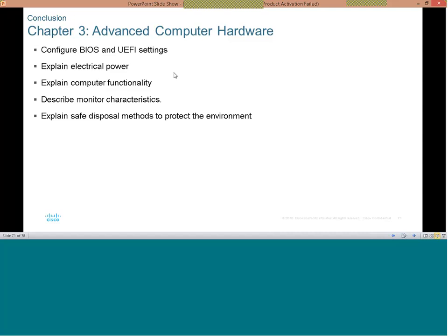And like I just talked about the electrical part of it, and then the computer functionality, because we need to know how the computer functions so that if there are certain faults in one area or the other, you know. Like for instance, if the CMOS battery fails, when you see your date actually not working well, you begin to suspect the CMOS battery.